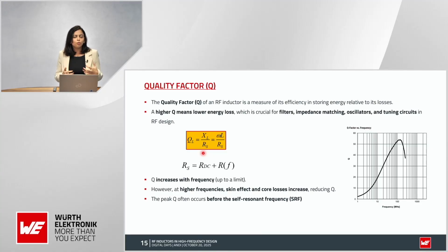And if we talk about a matching network, what does high Q help us with there? Choosing a high Q minimizes the insertion losses, making sure that our precious RF power is transmitted to the antenna and not getting lost while heating up in between.